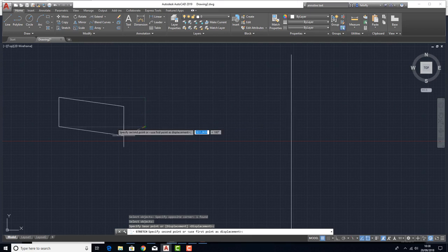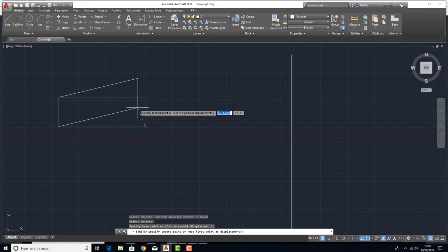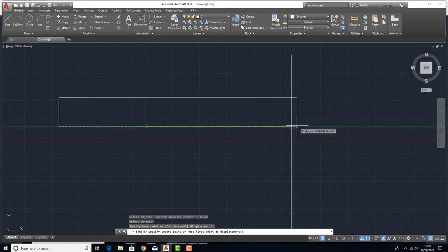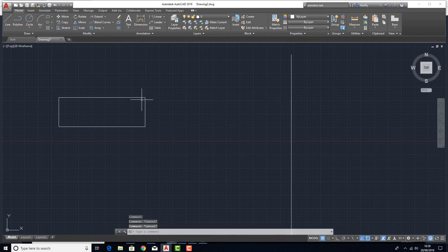Extend tends to extend a single point like a line. If you want to extend an object, the stretch command can be good for doing that. See there. Personally, I don't use stretch much. I prefer to use grips. If you select an object by shift clicking these blue boxes, think of these as grab points, then you can move it that way.